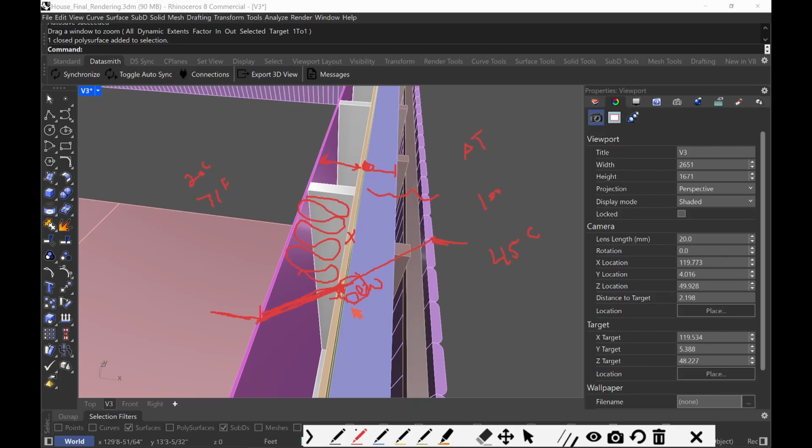Other people are saying no. If you provide ample insulation here, it's going to slow down the temperature difference where all the condensation will happen here and you'll be fine. If you look at product representatives and their details for recommended insulation, a lot of them will recommend both, because the product rep is more worried about the longevity and the warranty of the product than other factors like thermal comfort or sound, for example.